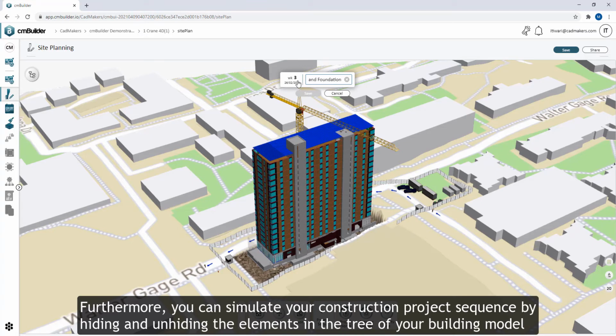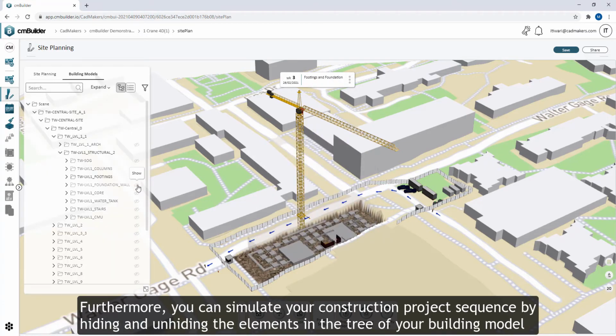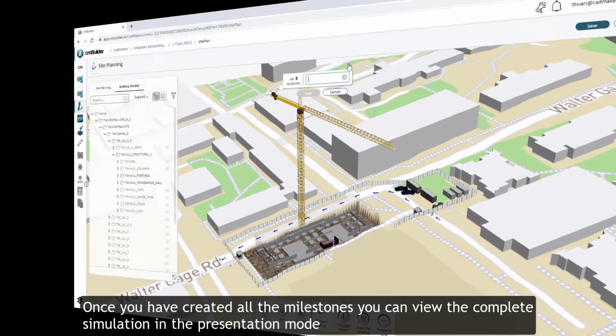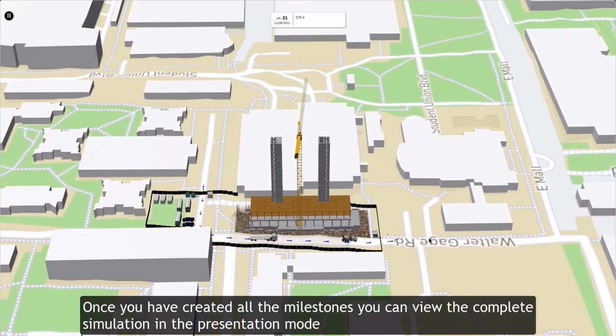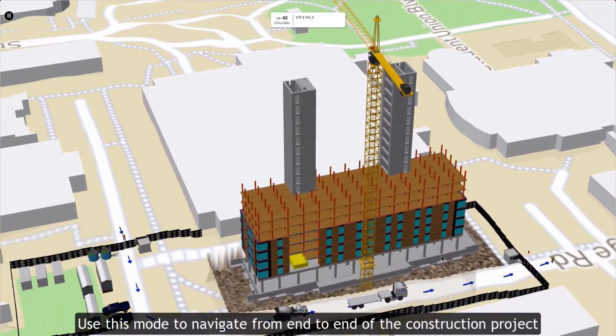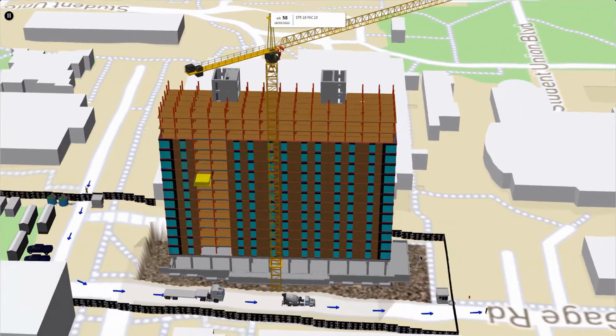Furthermore, you can create a simulation of your construction project sequence by hiding and unhiding the elements in the tree of the building model. Once you have created all the milestones, you can view the complete simulation in the presentation mode. Use this mode to navigate from end to end of the construction project.